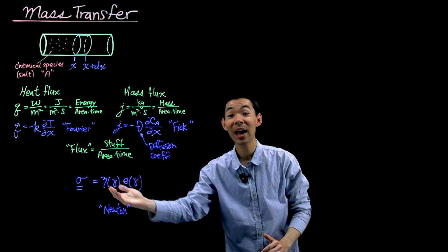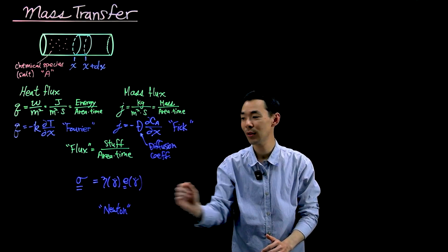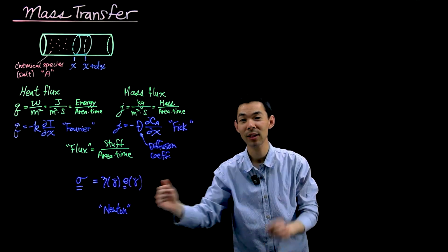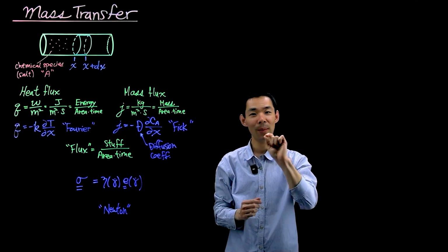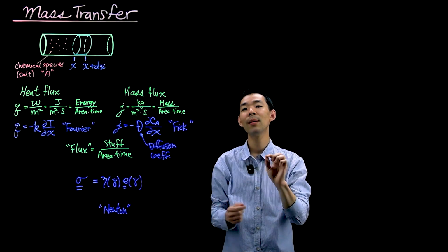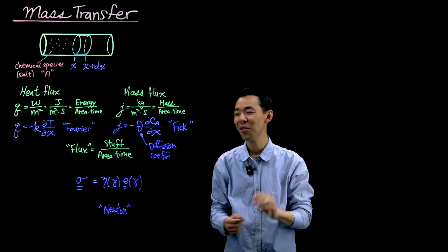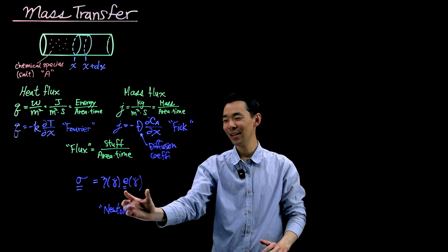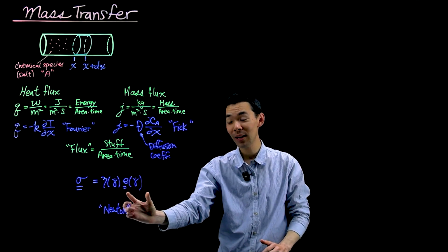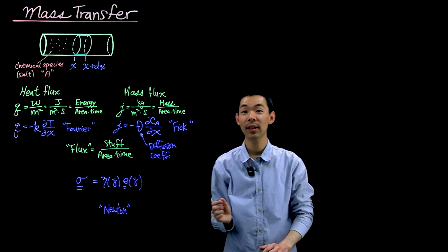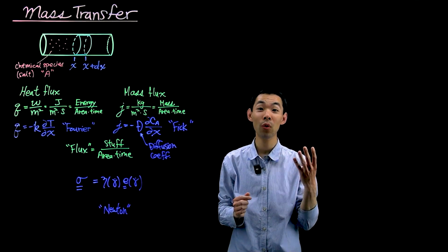So now we have tensors, which are called second-order tensors, relating another second-order tensor. That's why I have 2 lines underneath. A vector, I put 1 line underneath. Second-order tensors, I put 2 lines underneath. Now, in general, this relationship that relates what's called the rate of strain tensor to the stress tensor can be related by a 4th-order tensor.